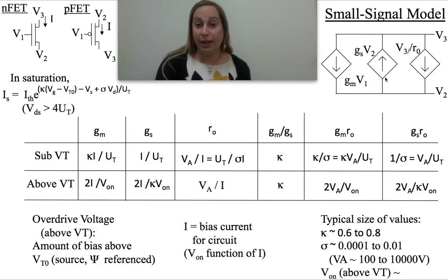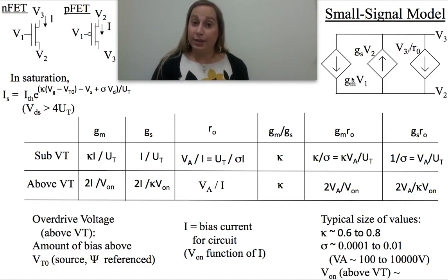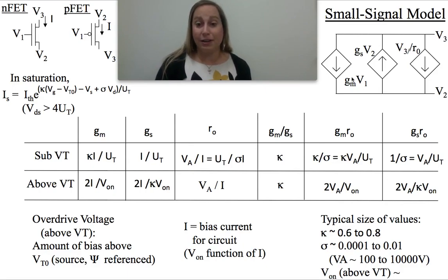If it was a common gate, that would mean that this would be at a DC potential and this one would go away, and so forth. And we'll find a lot of cases where the analysis is much faster, much more appropriate this way. So this is going to be the modeling we'll use. It really is actually quite elegant and quite simple to use when you do linear circuits.